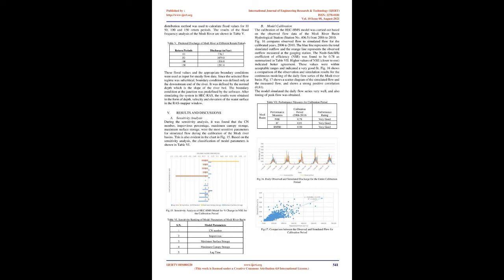Basin Model. In addition to building the model schematic in HEC-HMS, model components of the sub-basin were defined. Since the sub-basin element is used to convert rainfall to runoff, the information about the method used to compute loss rates, hydrograph transformation, and base flow was needed for sub-basin element. Table 3 summarizes the model components and the calculation method selected in this study.